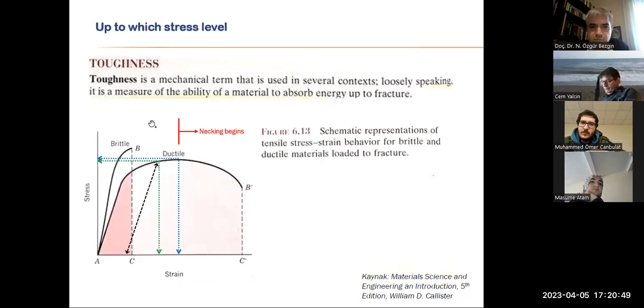So coming back to our stress strain graphs, we have the ductile material, we have the brittle material, right? So we want ductility. It is good. We all agree on that. So what happens after the maximum? We have the region where necking begins. So we would rather not use this region at all because the structural element, which is basically steel in this case, is just on the road to complete fracture. So this is our maximum, and this is the maximum that is being referred to.